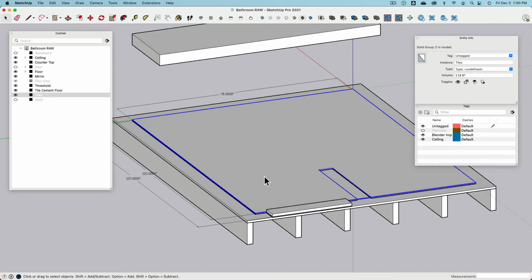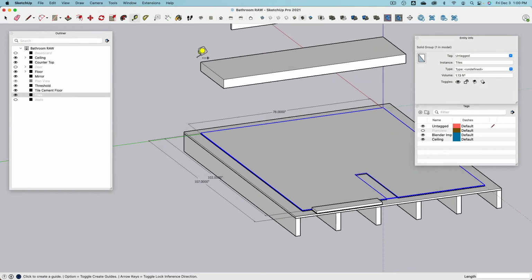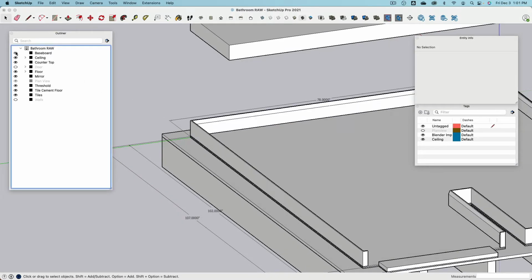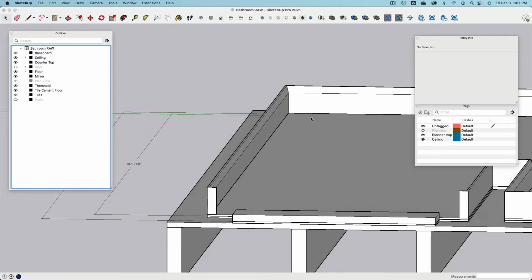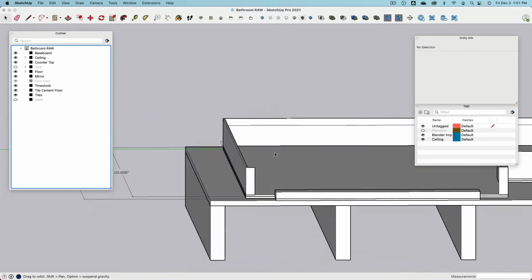And that is very, very important because keep in mind later when we position our sink or countertop, we want to measure everything to certain distances or heights. So that's like 32, 2.5. Now you see there's a little bit of half of an inch of an offset. In my model, I have the baseboard sitting right on top. Technically speaking, we want to have the tiles run inside the baseboard, so in case something pushes on the baseboard, it doesn't crack the tiles.